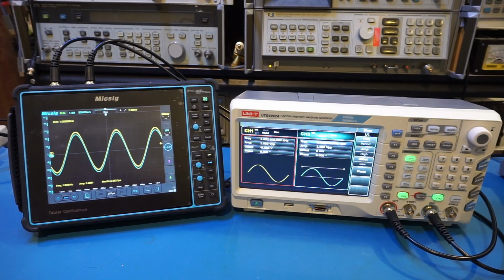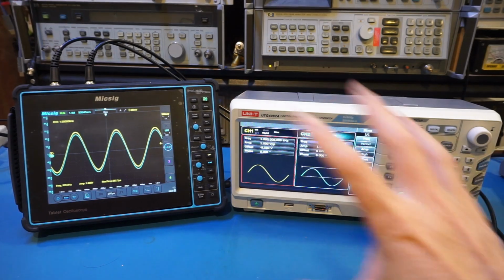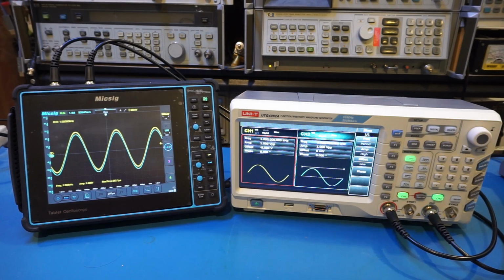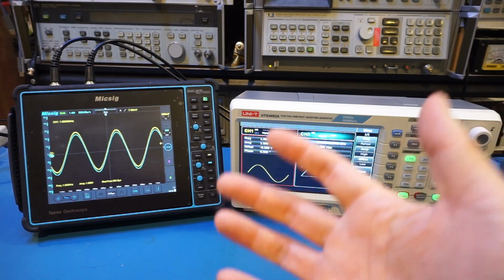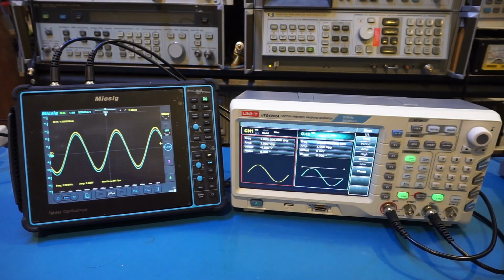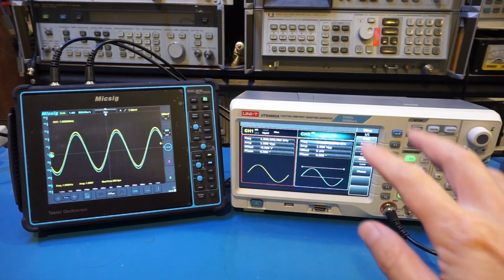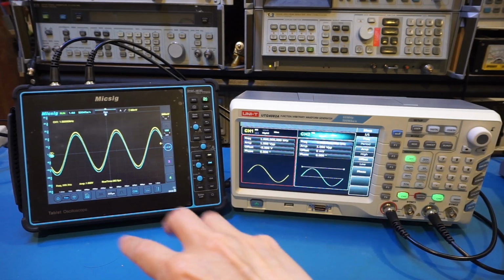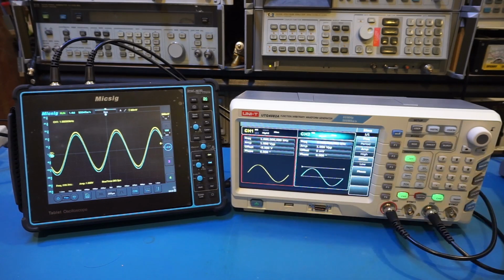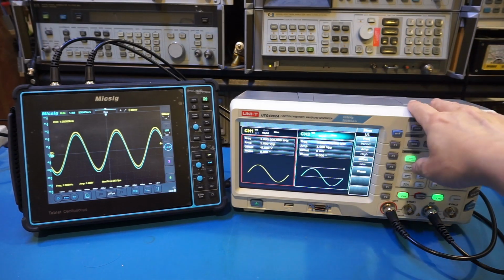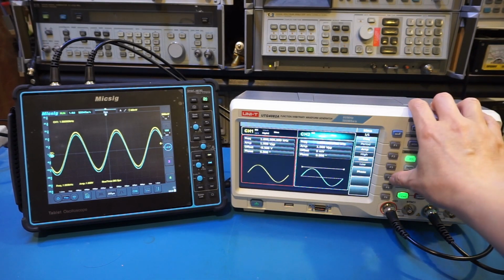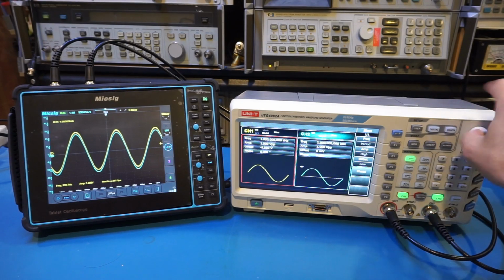And of course, the 4082A is a dual channel one, so we should be able to use both channels. One useful application is if you want to generate 2 signals of known phase difference. So let's take a look at that demonstration here. Right now, I'm outputting 2 1 kHz sinusoids. Both are in phase currently, and we can adjust the phase of one of the signals. Let's do phase 2, for example. We can change it 1 degree at a time.